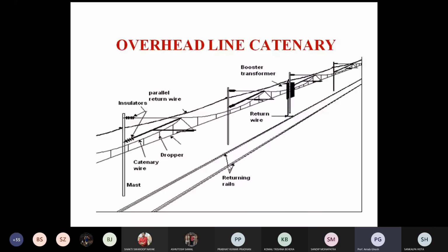kVA. Okay, so normally 100 kVA, as per the total number of houses connected with that substation. Again, DY11 means input is delta and output is star. Star means R, Y, B is there, and another neutral. That neutral is directly grounded over there. So one ground is your generating station, another ground is your locality.